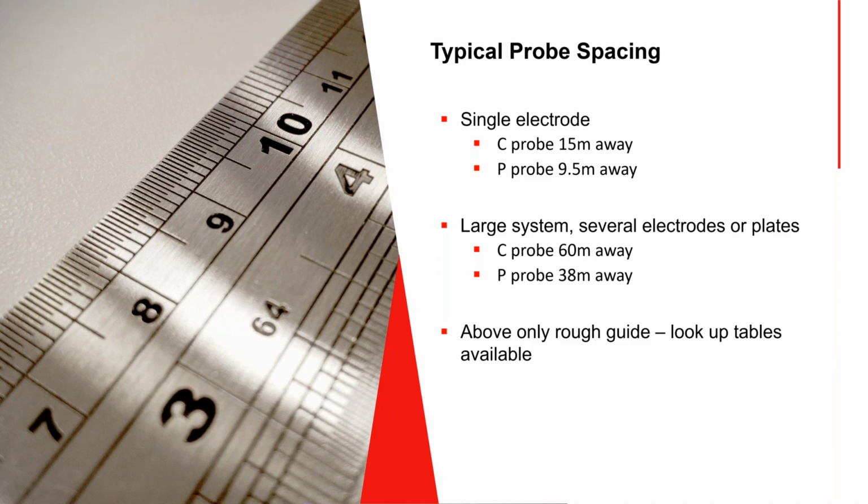If you don't have that distance, let's say you calculate against a table and it tells you that you have to go out 500 feet with your current probe, and you don't have 500 feet, you have 350 feet. Okay, do your test at 350 feet. If you get a good result, you're good. Don't worry about it. You've made a good test at 350 feet, and that's fine. So the tables are just suggestions. They are not scientific demands. Next.